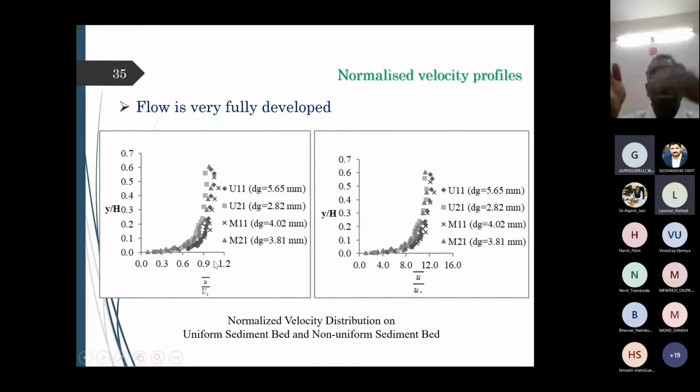For example, you have collected data in our working section at 3 particular cross sections: cross section 1 upstream, cross section 2 intermediate, and cross section 3 further downstream. If you collect the data and make the plot, and all the data points from the upstream section, intermediate section and downstream section follow one particular velocity profile, then you can say the flow is fully developed. If it is not, then your flow is still under development stage, and you cannot say that it is fully developed, and we cannot use your data for our work. You getting the point?